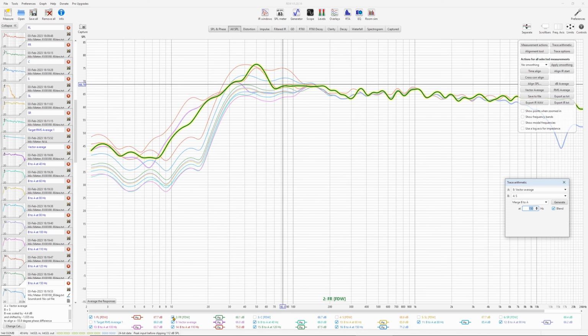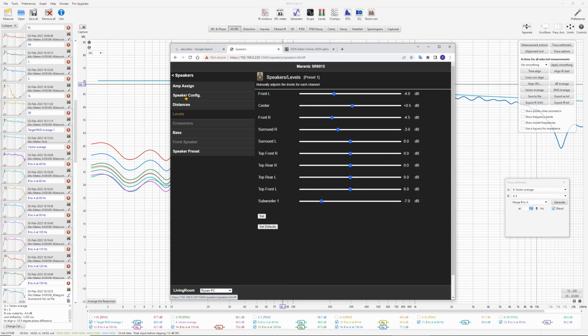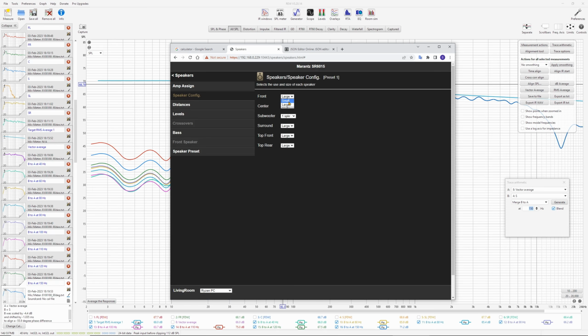And now with everything cleaned and the target there, where's our target here, which one do you think is the correct one? It's very obviously this green one here. So you cross over your fronts at 120 Hertz. That's it, that's so simple. And go there, go to speaker configuration, change this to small, and cross over 120.